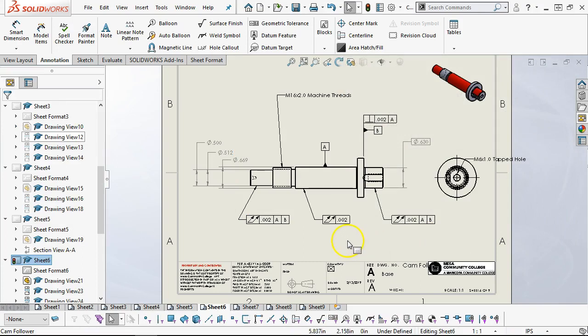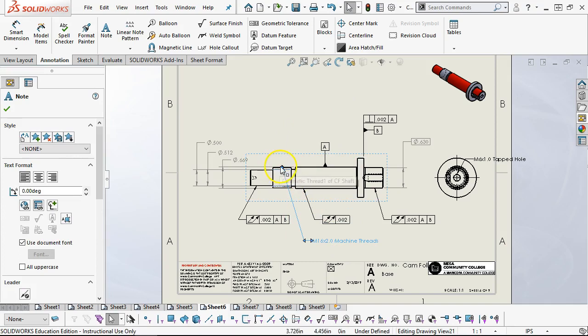All right, so the other key interest is if we wanted to take it far, I think it's about as easy to have the run out across this entire surface. Otherwise, we could give it the half inch or so that's going to contact the bearing, the half inch on this end that's going to contact the bearing, and say that the run out is from this distance to this distance. All right, since we're not talking about an extreme amount of length, I want to say we'll just leave it and come back to that one later.